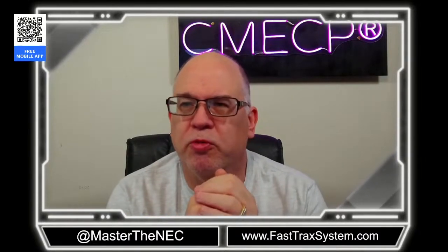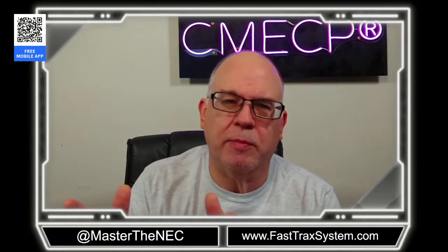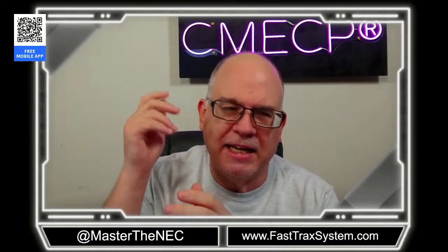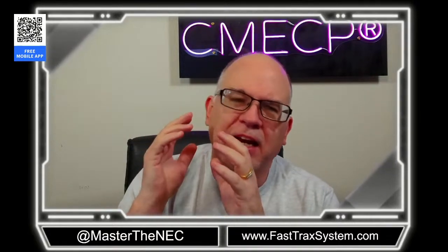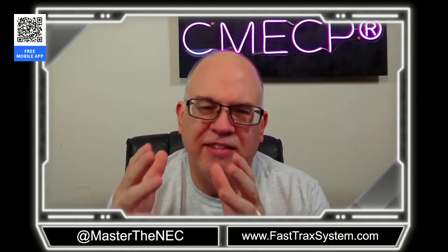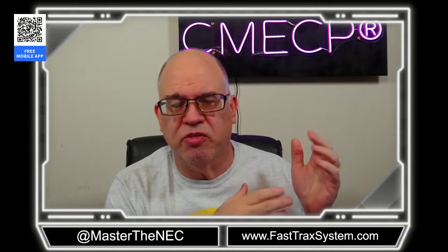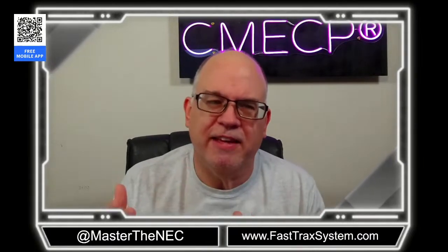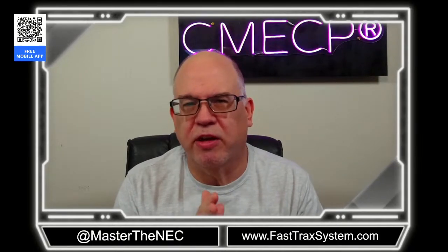And of course, first responders have to respond. We don't want them going into houses searching for ways to cut the power off. We also don't want them hacking up the service conductors or the meter or trying to pull a meter. They're not electrical experts, so we don't really want them working with those energized live parts that typically are not going to have any overcurrent protection ahead of them. So it creates a safety concern. That was the justification for why it made it into the National Electrical Code.